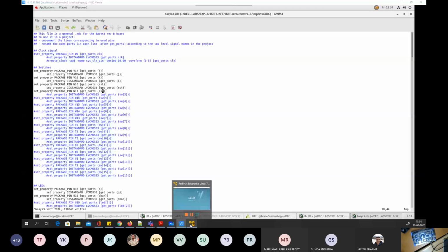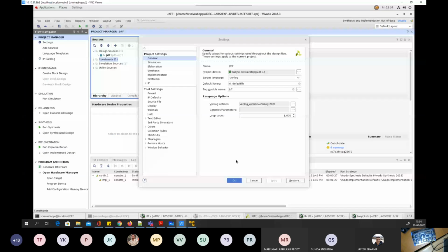So here the whole idea was, just to summarize what we did so far. Given a D flip flop, you can write Verilog code for it and a test bench for it. You can simulate it using iVerilog and GTKWave or ModelSim, writing a test bench to simulate it.